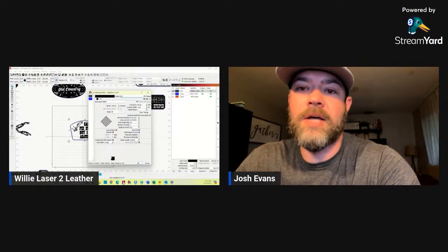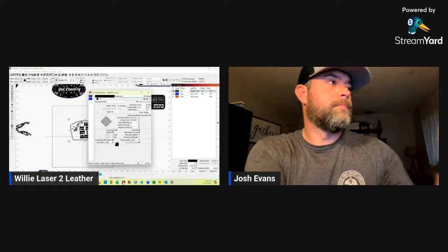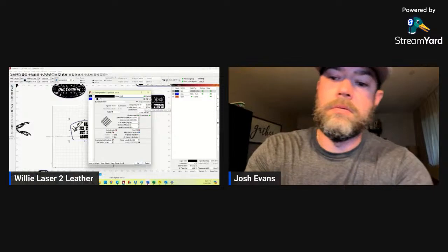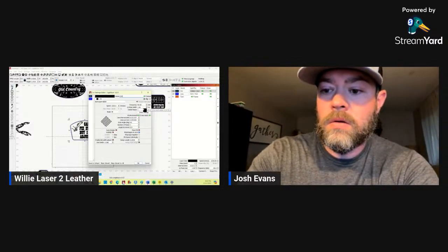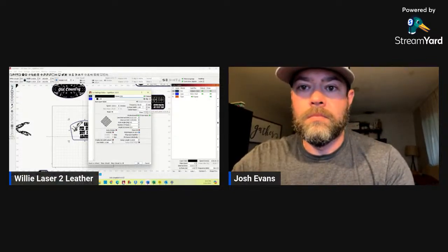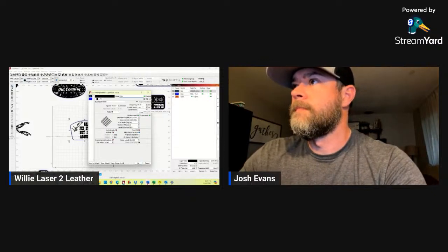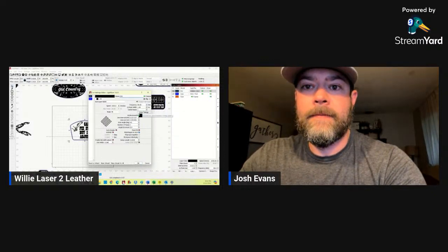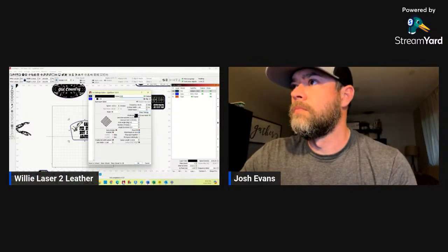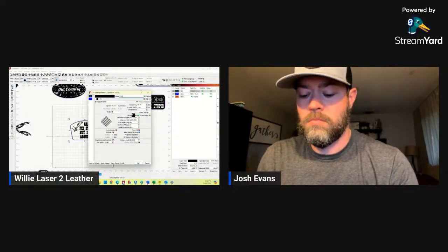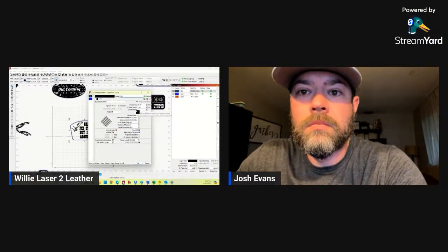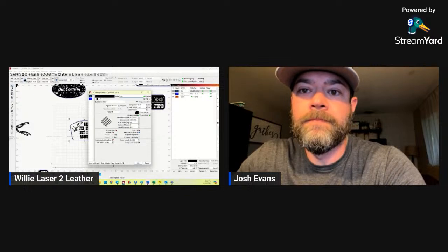Gotcha. So your power is a constant. Yeah, your power always stays the same. The Q pulse, I don't use it a lot, but some people do. It ranges from 1 to 3 most of the time. What it does is, on your frequency, the frequency is counting your top end spikes, if you're looking at an oscilloscope. The Q pulse is actually the bottom end, and it's the length of time that the laser is actually pulsing. So you have the number of pulses and then the length of time that it's pulsing. That's where the Q pulse comes in.